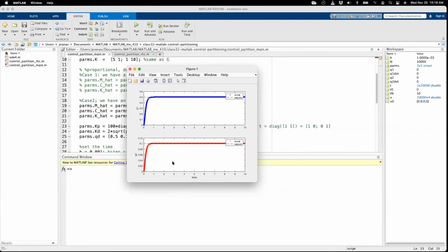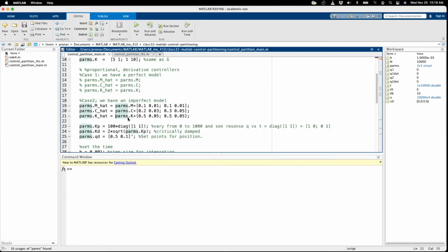And now you can see it's much better. It's actually following pretty well. The response is also within 1 second. So here is a perfect example of why we want to do feedback control. That is, our estimates for the system dynamics are imperfect, and by putting a high enough gain, the system is being regulated to the value we care about. Okay, I'm going to stop sharing, and we'll go to a physical example of a pendulum.